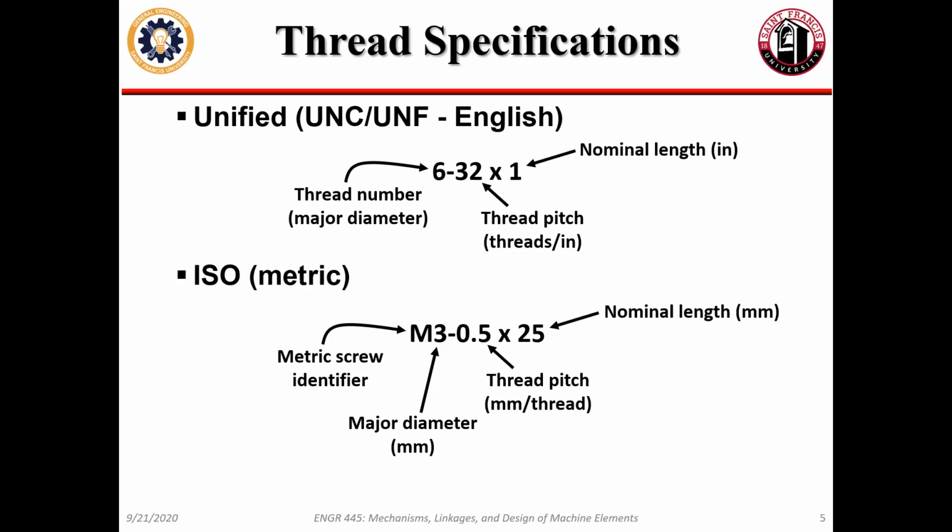Now, can you figure out what a thread is called just by looking at it? Yes, because everything is defined in terms of diameter, pitch, length, and if there's a taper, the taper angle. So you can definitely figure it all out if you have a pair of calipers and an example of whatever you're trying to find the measurements of. So that's a super handy thing.